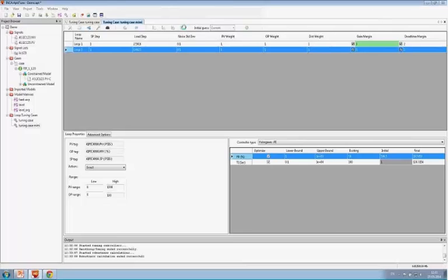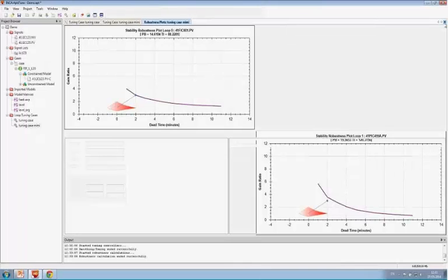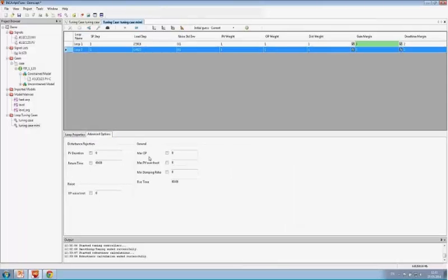And of course for the diagonal, for both of the controllers, we have our robustness plots, with which we can judge how robust we have tuned these controllers. So this is all the same as a SISO case, only in MIMO, and you have to make the same judgment here. And now we will move to, let's say, the advanced options.